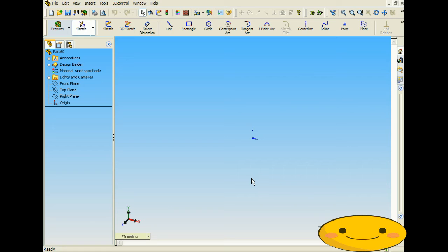So pretty much what the 3D Sketch allows you to do is flop around between which plane you're sketching on. If you called each plane an XY, an XZ, and a YZ plane, you're able to toggle in between all those planes. To start off, you have to click 3D Sketch and then click whichever tool you want to use.